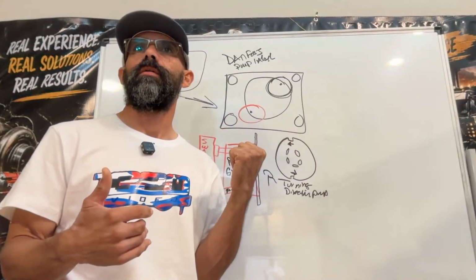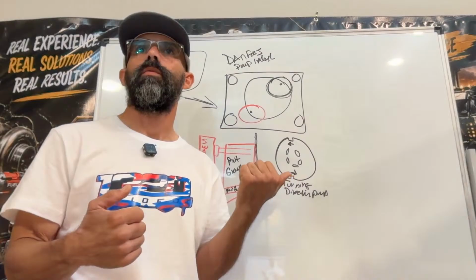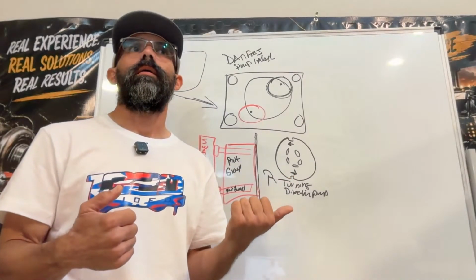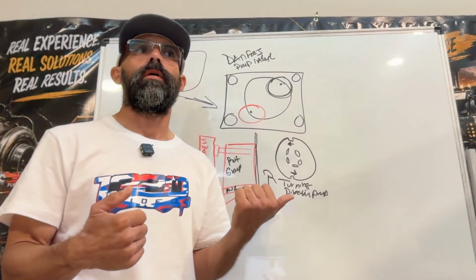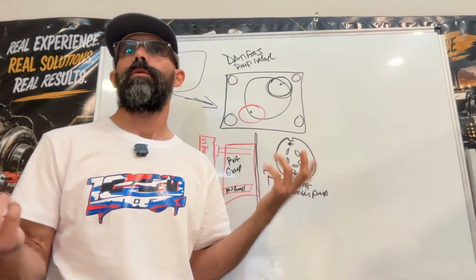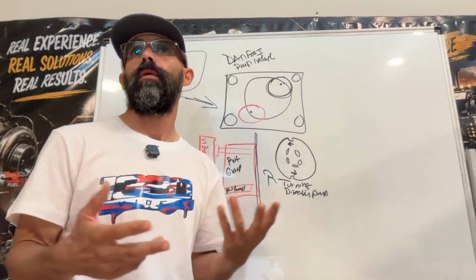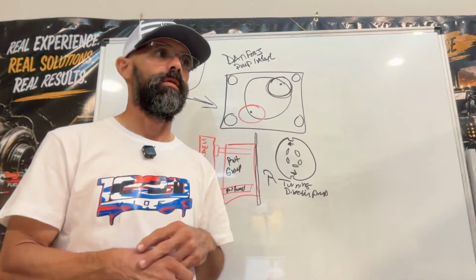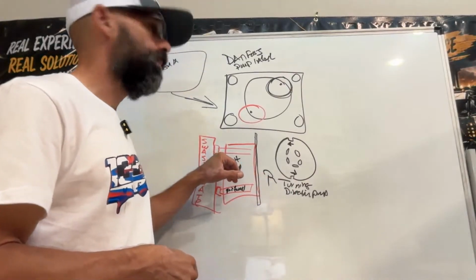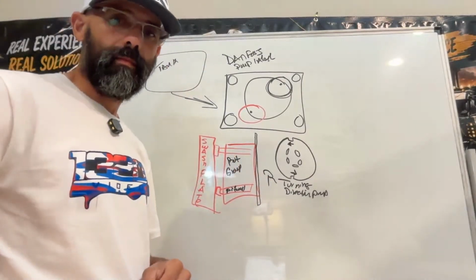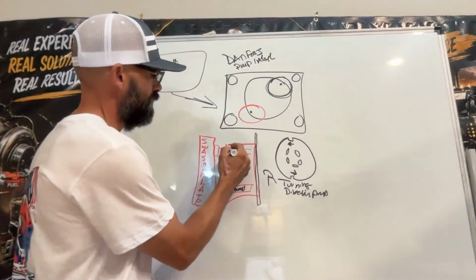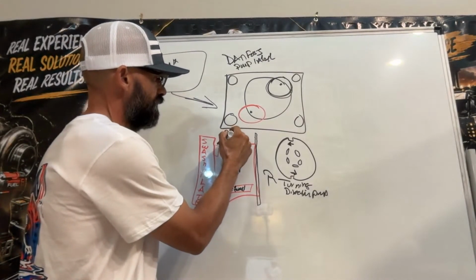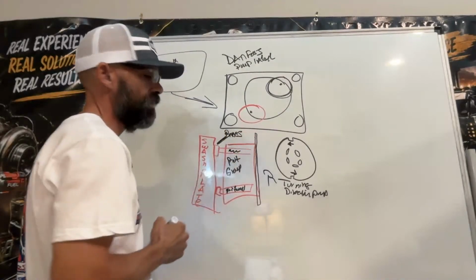It failed because it was worn out, because one of the swash plate bearings got damaged. It broke because maybe the spring on the servo failed, or it was starving of oil, or because one of the slippers or pistons broke off. This is all metal, but the head of the slipper is brass material.